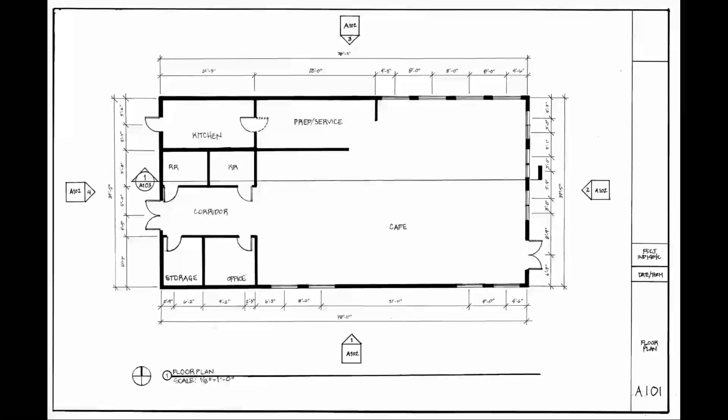Sometimes, if the section line overlaps too much stuff and it becomes hard to understand, you can break your section tag here and here and get rid of the line in the center, and that will clean things up a little bit. You'll see that later on when you learn Revit. But for right now, this is a very simple, straightforward section tag.